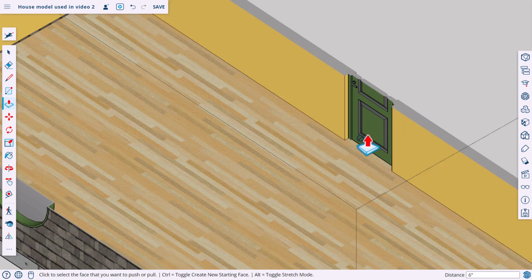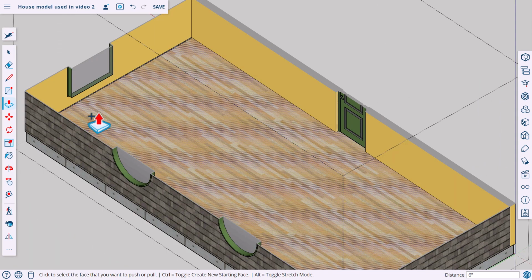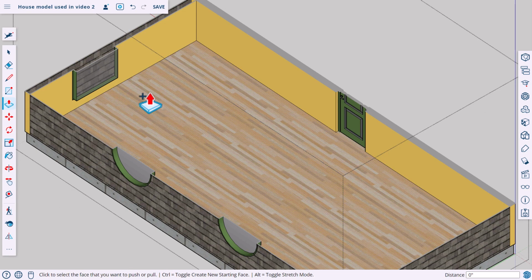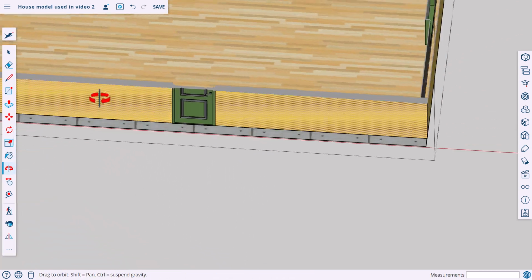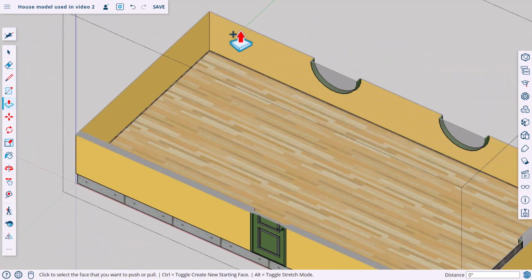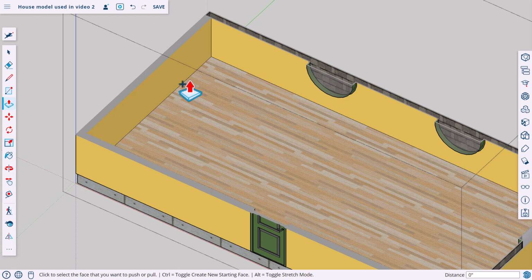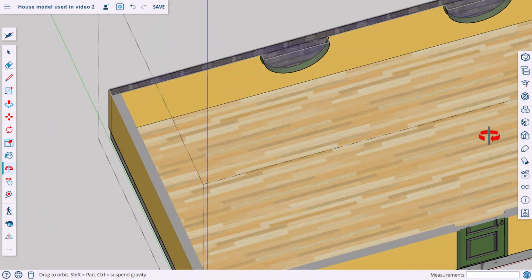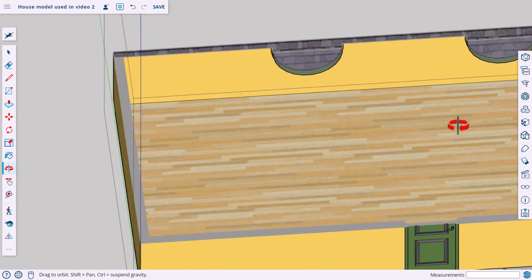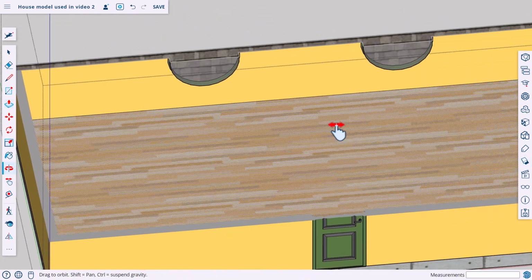And this works great with the door, because if you remember, I had to create an opening for that door. However, it doesn't work nearly as well for these walls. I'll just double click on it to give it a 6-inch wall thickness. And in fact, I can go around and I'll do that for all the walls, double click on them to create a copy that makes a 6-inch wall thickness. And the problem is, you can see right here, the windows don't go all the way through the outside of the wall. And that's the problem.